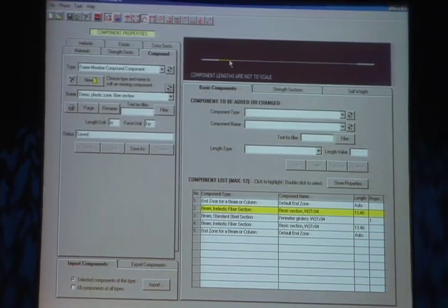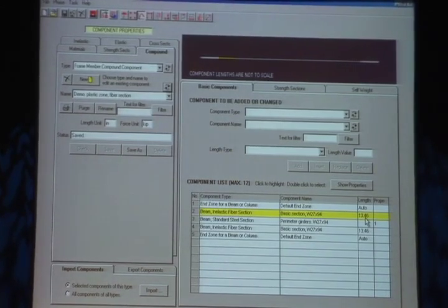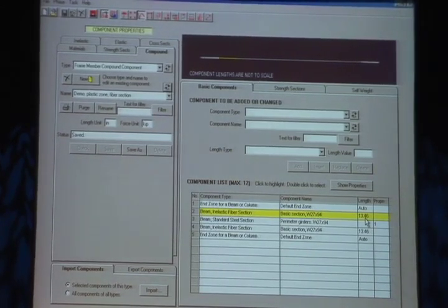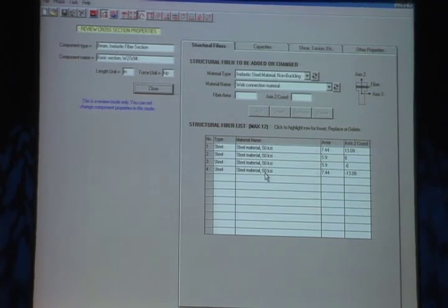Next thing we can use is a plastic zone model with a fiber section. And here there's a short length of fiber section, which is now 13.46 inches, 1/2 the depth of the beam. And this is using a fiber cross section. And if you want to show the properties, this happens to have just 4 fibers, 1 for the flange, 2 for the web, and 1 for the bottom flange. You could use more if you want, but 4 probably is not a bad idea.